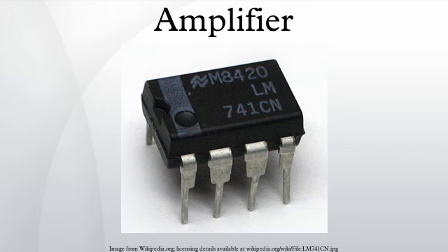The amplifying element is biased so the device is always conducting, and the quiescent collector current is close to the most linear portion of its transconductance curve. Because the device is never off, there is no turn-on time, no problems with charge storage, and generally better high-frequency performance and feedback loop stability. The point at which the device comes closest to being off is not at zero signal, so the problems of crossover distortion associated with Class AB and B designs are avoided.